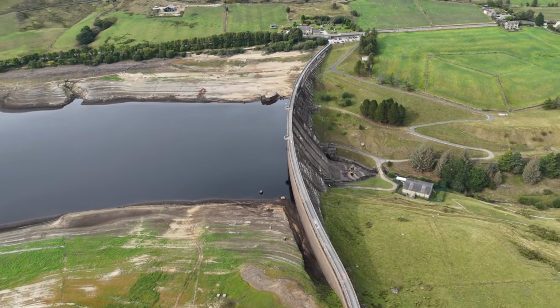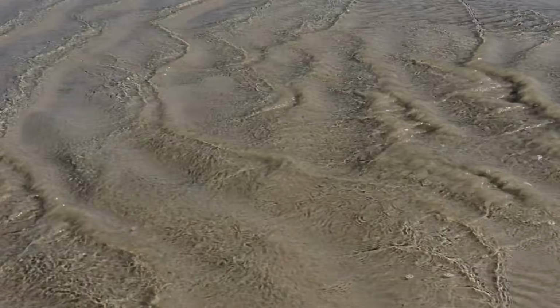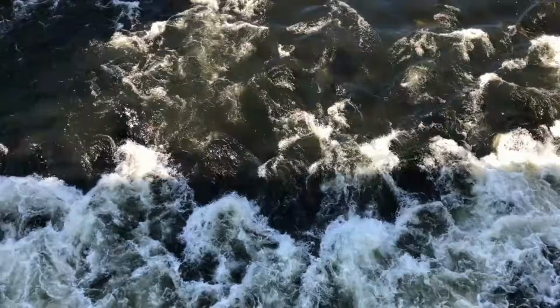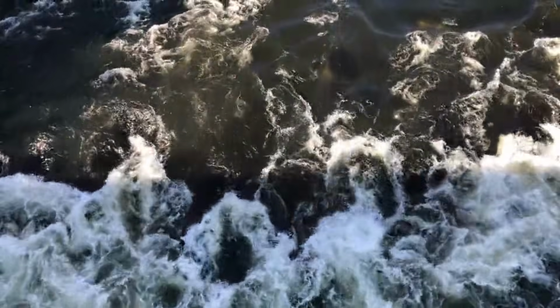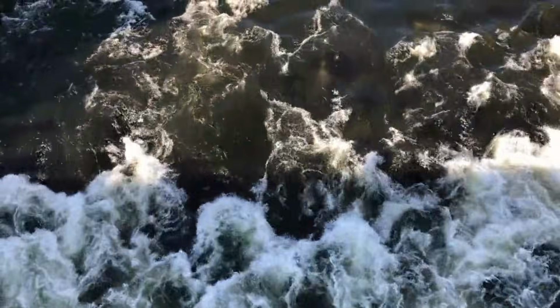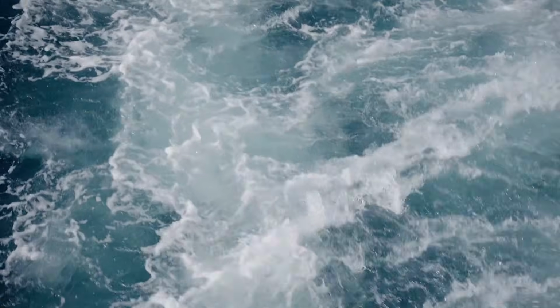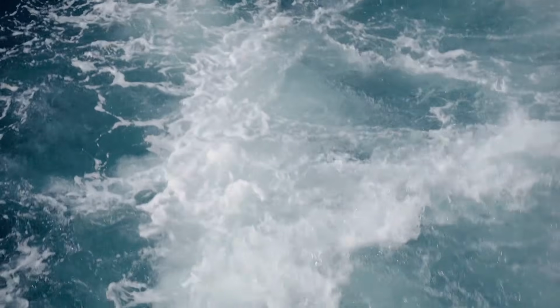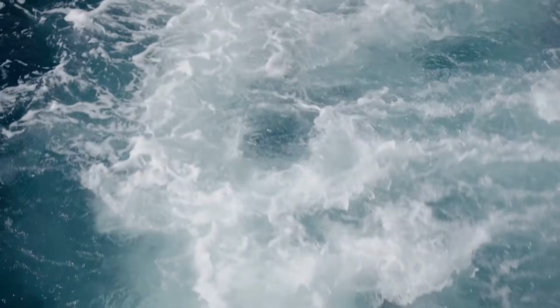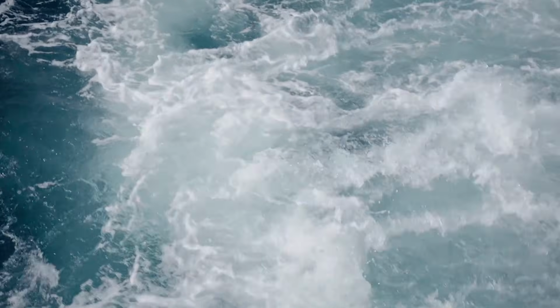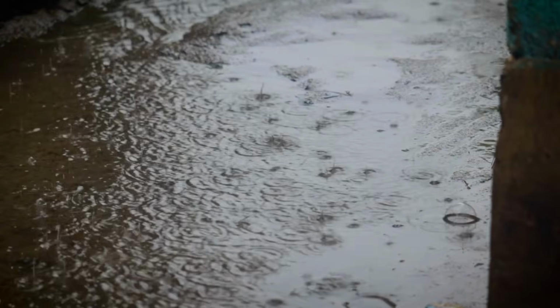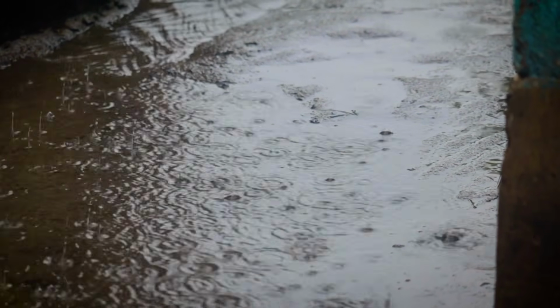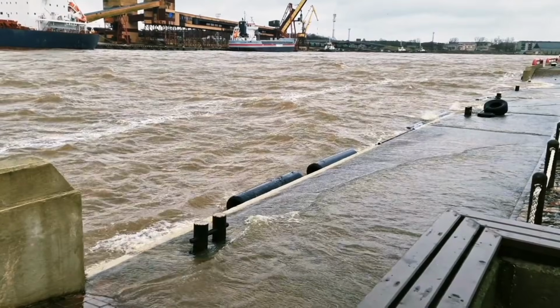This creates a phenomenon known as a bore. Unlike a wave on a beach that rolls over and breaks, a bore is a self-sustaining wall of turbulence. It maintains its shape because the high-velocity water from behind is constantly crashing into the slower, shallower water in front. This creates a hydraulic jump that travels. The kinetic energy isn't dissipated quickly. Instead, it is concentrated at the very front of the wave, which acts like a liquid piston, pushing air and debris ahead of it with the force of a localized hurricane.